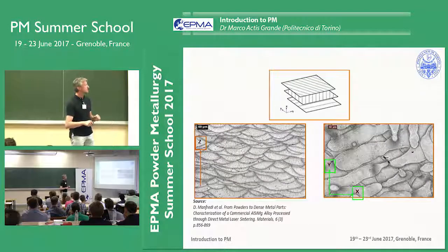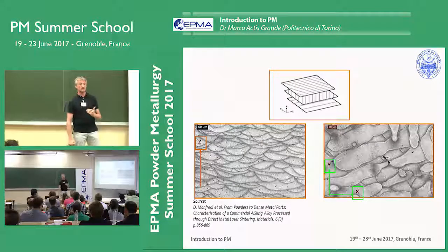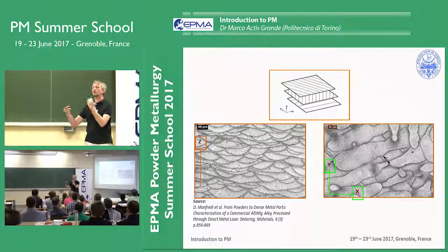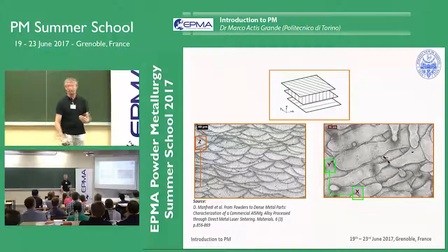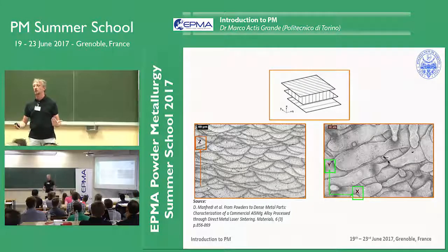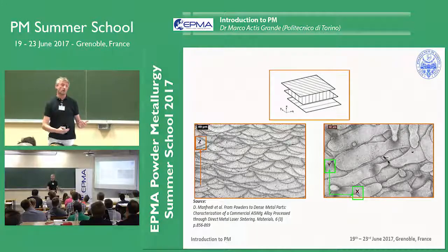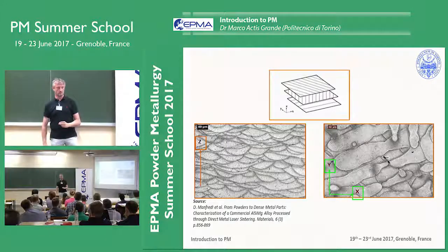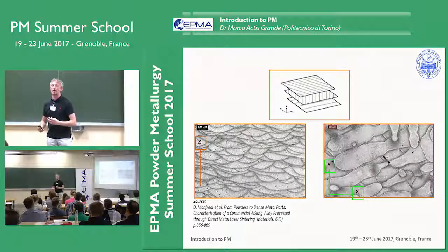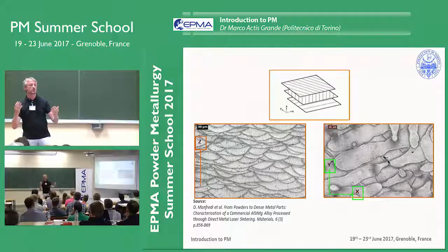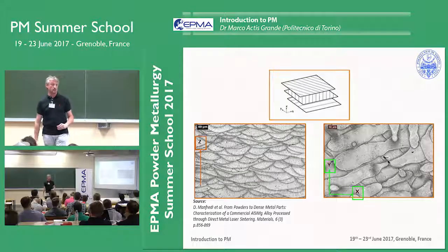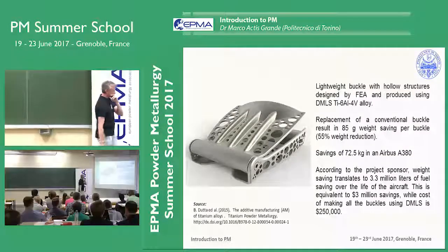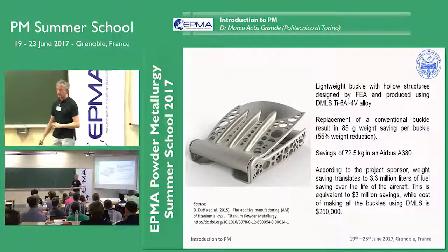Why? Because in this case, we are creating something which is first melting. In which way? Layer by layer, or let's say a couple of layers every time. And what is this resulting into? A microstructure which is totally different from what you can get from the traditional metallurgy, but also from what you can get from the powder metallurgy. So the point here is we start from powder and we get something which we have to rediscover, or reinvestigate from the very beginning, or sort of. Of course, there are plenty of works, plenty of research being done in that field.